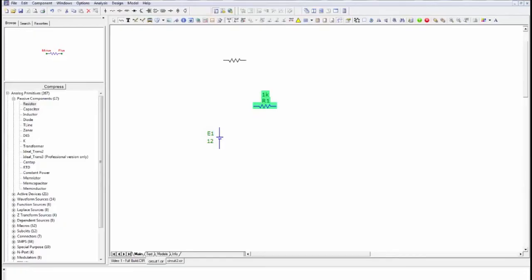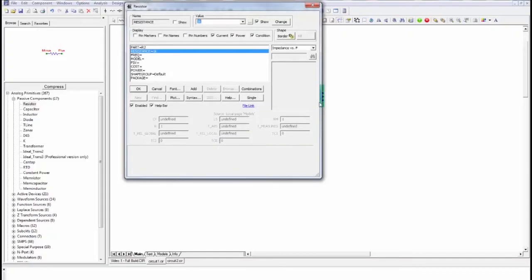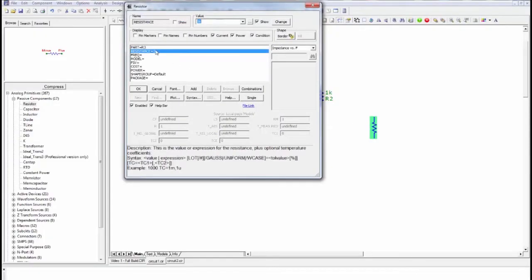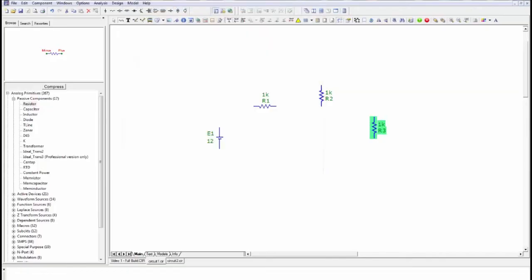And there's the resistor. Now by default the simulator assumes you want another resistor, so straight away you have one on your cursor. So move the cursor around. I'm not touching any buttons at the moment. So why don't I left click, right click, and I've got it oriented the way I want. It also assumes you want the same value as last time, which in this case you do. So it's got 1k up here, which is fine. I want another 1k. That's oriented the way I'd like it, which is good. So left click, place. Again, it assumes 1k, which is good. Put that in there.